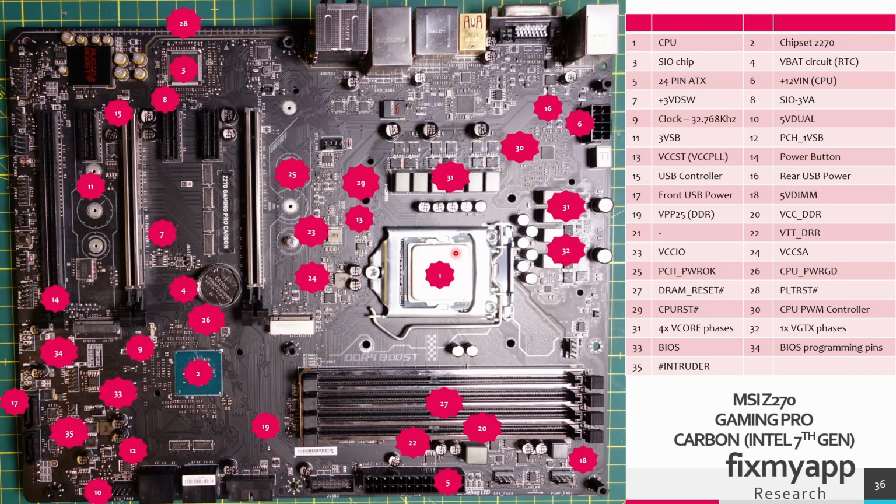The CPU has to communicate with this PWM multi-phase driver controller to specify what kind of core voltage this CPU needs. So the SVID, the serial voltage identification, is an interface protocol used between the CPU and this multi-phase PWM controller. This multi-phase PWM controller is responsible for generating the VCORE voltage that will be used by the CPU.